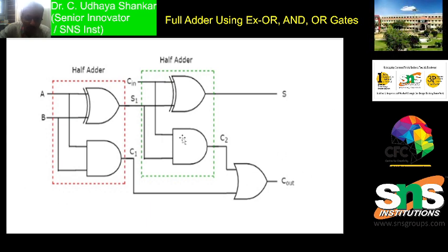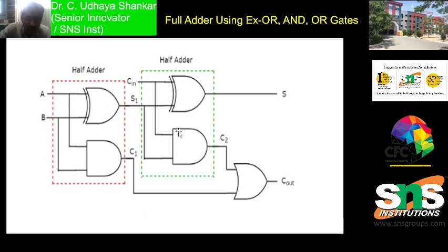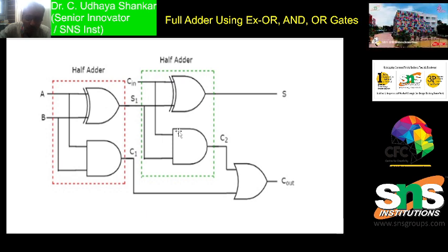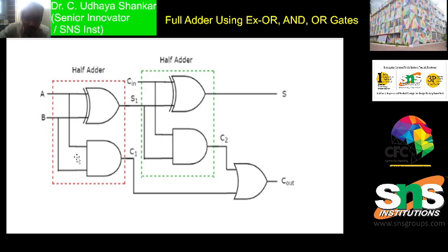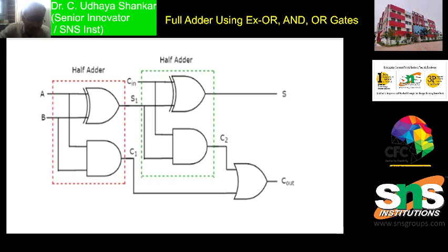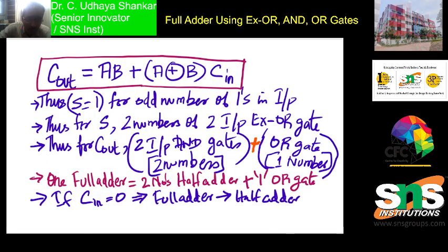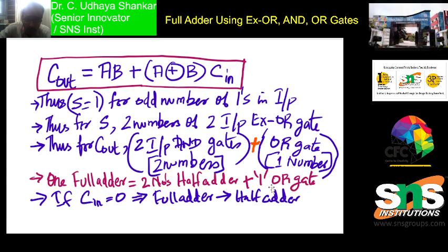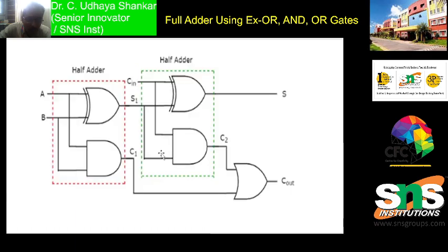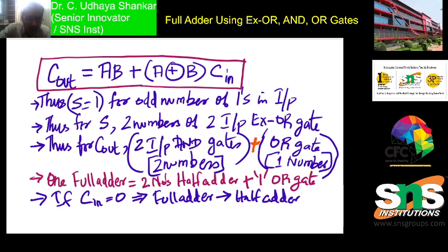So finally, we will be getting the circuit where full adder will be equal to the combination of 2 half adders, along with that one OR gate is needed. So this is what finally we have concluded. So it needs, for a full adder, 2 half adders with 1 OR gate. Here I have written over here: 2 half adders with 1 OR gate. So we have achieved it.